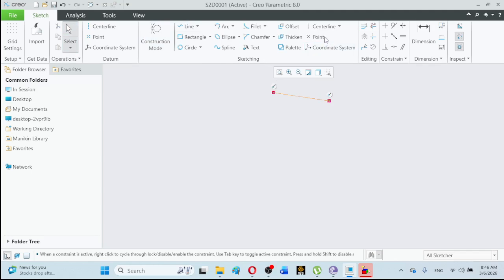So here if I try to draw the third point, we can see that it is showing the trace at this location. This third point is falling in collinearity with the previously drawn 2 points. So this third point cannot be collinear, neither here, nor on this line, anywhere. It must be away, either up or down, on either side of this line. So here, for example, I have randomly drawn this third point. Now I can launch this 3-point circle command.